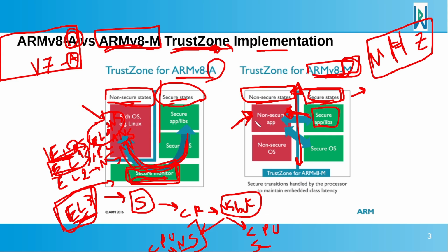Similarly if we want to switch from non-secure to secure. So the tagging or the attribute of the destination address will have an impact on the CPU state, whether to be secure or non-secure. Hence, we are minimizing the backup and restore routine needed in case we want to switch via an intermediate mode. So this will not be the case on the ARMv8-M architecture.